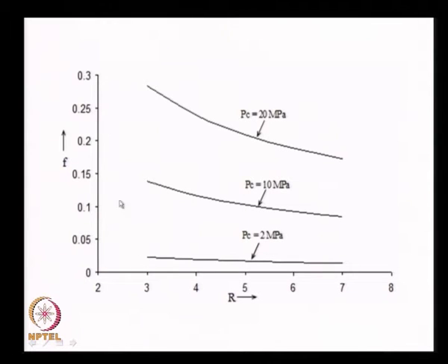Second is the same thing. If I now translate into chamber pressure, I find that the fraction of the propellant which flows through the gas generator and is not expanded adequately is large at high chamber pressure. For this particular example, I took the mixture ratio of the gas generator as something like 0.6, the overall mixture ratio of the engine as something like 4, eta P as 0.6, and the temperature of the gas generator as something like 900.